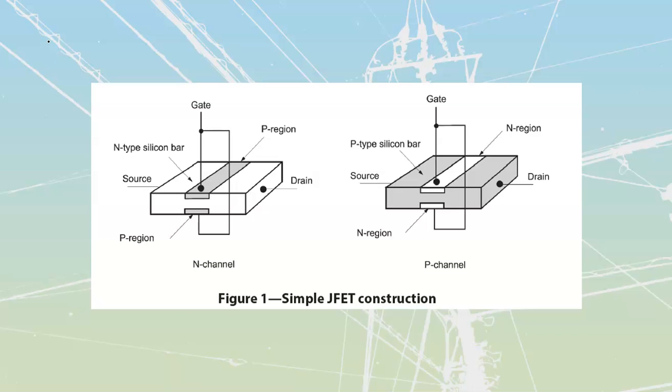Field effect transistors are different in that they have two main things. One is that they are unipolar. This means that all of the current is going to travel through one region. It's either going to be my P or my N type of material, compared to my BJTs where I would cross over those depletion regions, P and N types of regions over there. The other one is that it is going to be voltage sensitive. They are going to be controlled by voltage, not by current.